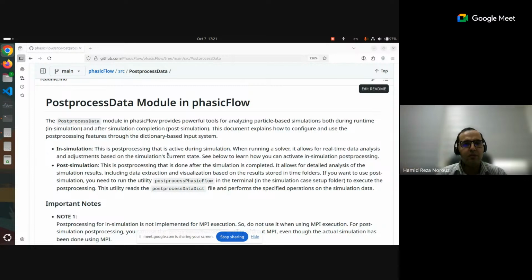You do the post-processing operation at the same time, from the data that is available in the RAM of your computer. This is useful when you want to do the post-processing more frequently than you want to save the data of the DEM on the disk.